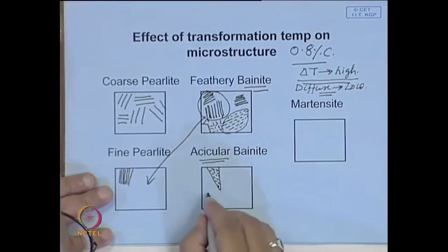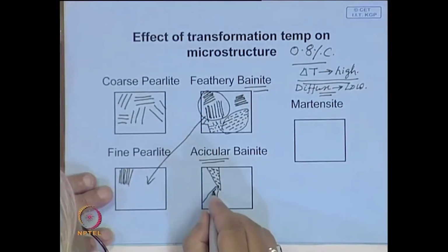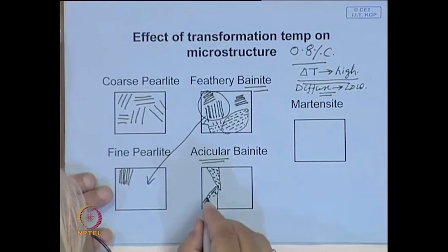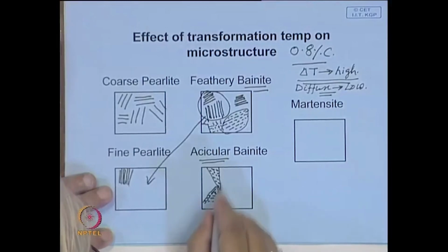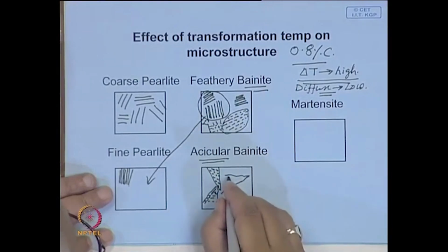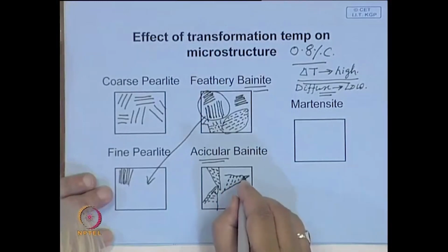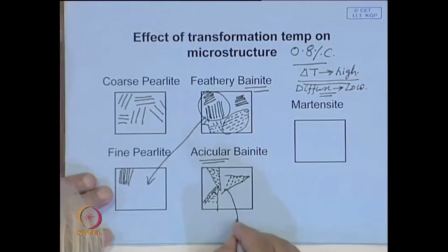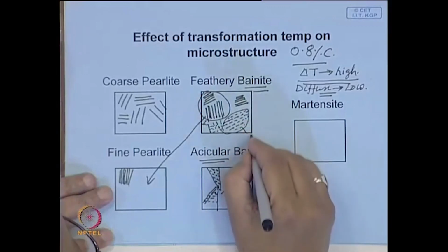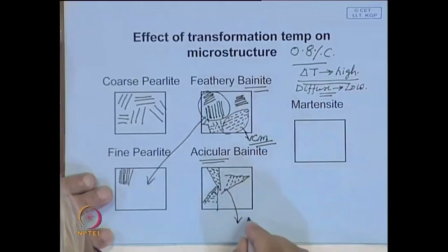So, what you see is you will have some plates of ferrite nucleating, and within this, since the carbon atoms form at a particular angle to the direction, it means needle like. If this is the shape of a ferrite grain, you have this carbide which is precipitated like this, and I think it was mentioned this carbide here is cementite, and this carbide is called epsilon carbide.